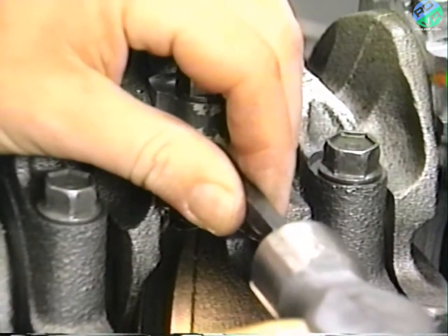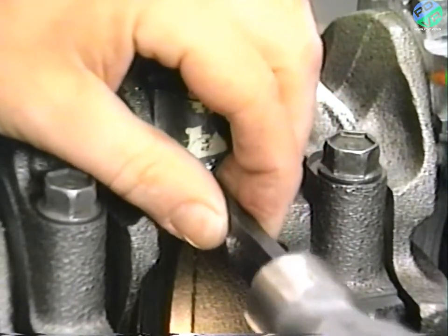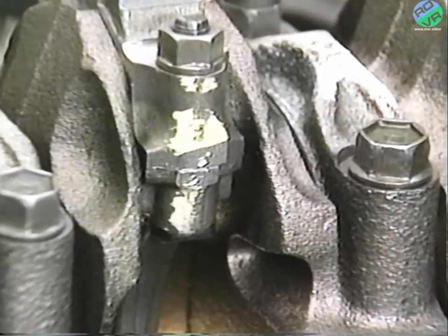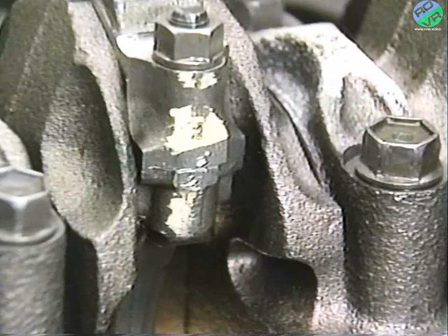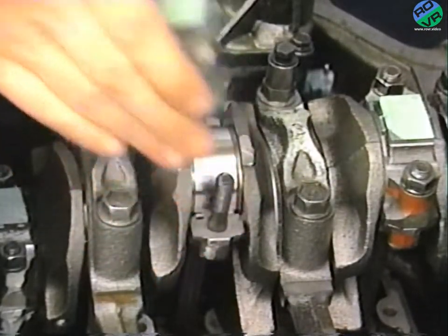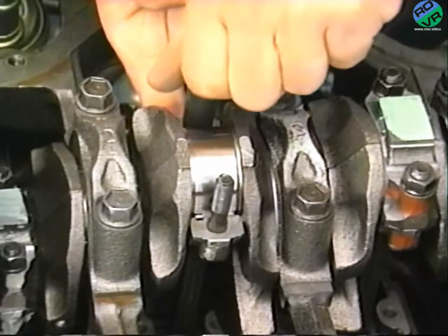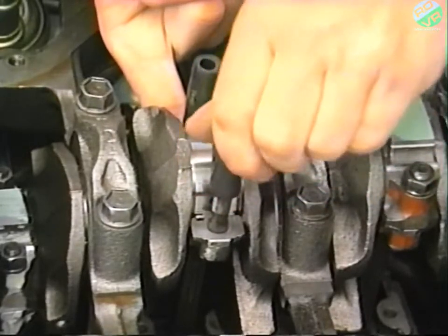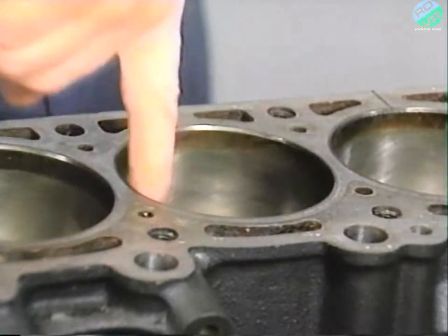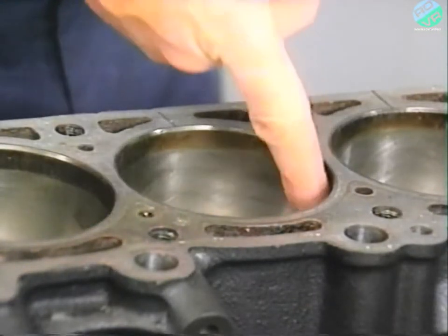Before removing pistons, connecting rod bearing caps should be numbered and arrowed for direction. Relieve torque evenly by loosening the nuts in steps, following the reverse of the tightening sequence. Before pulling the piston and connecting rod out of the block, cover the connecting rod bolts with short lengths of rubber hose. This will prevent scratching the crankshaft journals. Also, check the cylinder for a ridge. Use a ridge reamer if necessary.